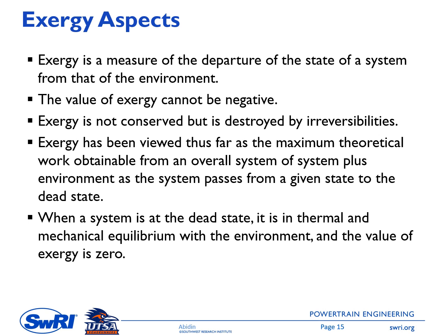Okay, so the value of exergy cannot be negative. Why? So if you have a system that is different from the environment and you just let the system go and then come into equilibrium with the environment, so it means you get nothing. So it means exergy is 0. Because you just let it go, you just let the potential go and then you get nothing there. So it means exergy is 0, but it won't be negative.